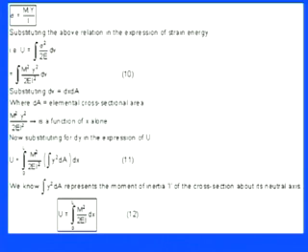So U equals the integral from 0 to L, because M squared y squared divided by 2EI squared was only a function of x. So again 0 to L of M squared by 2EI into dx, because the integration of y squared dA gives you I, and that I is cancelled out. Now we can calculate the strain energy under the bending action, which focuses on what the bending moment is and what the flexural rigidity of that material is.